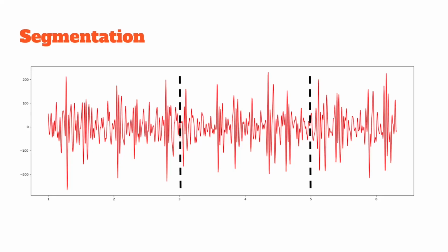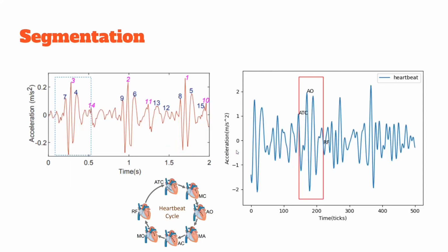We then try to segment out the heartbeats in a section. The heartbeat cycle contains features such as AO and RF. These features can be found to correctly segment the heartbeat pattern. In each 2-second interval, we will extract a single heartbeat. We do this by identifying the AO and RF using the shortest distance between 2 peaks that's greater than 200 ms starting from the highest peak.